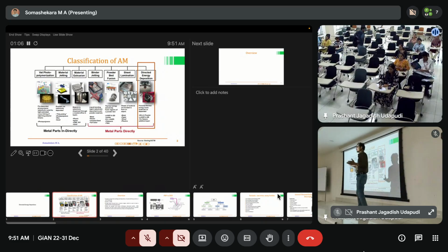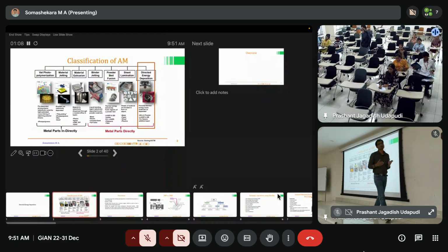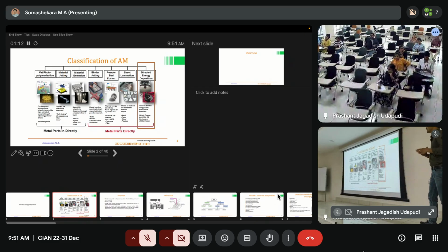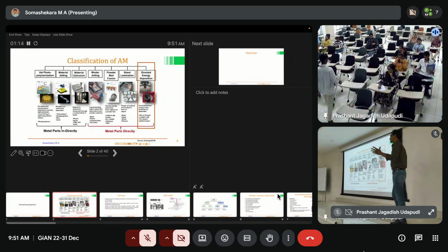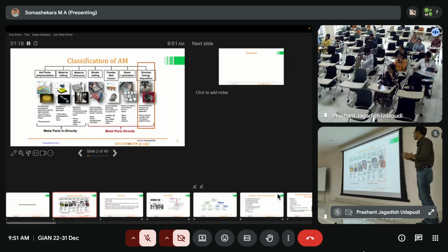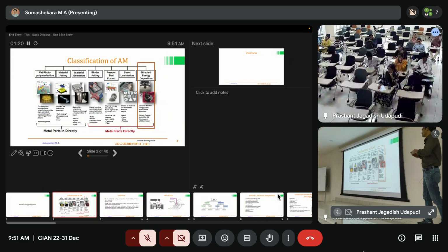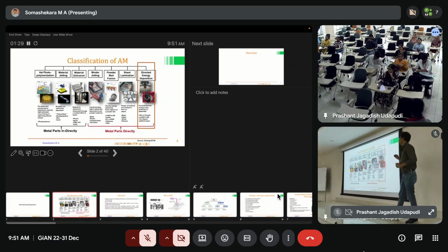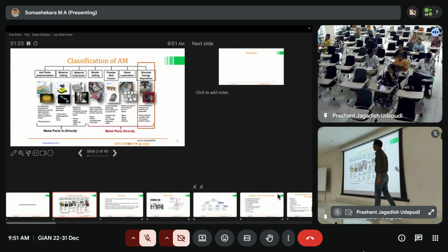Which means, for example, if I want to play with multiple materials, or go with a larger scale in terms of the size of the print, you want to print a bigger component. It will take a lot of time, because as I said, one of the constraints that we have is the size of the powder, right? The size of the layer thickness.